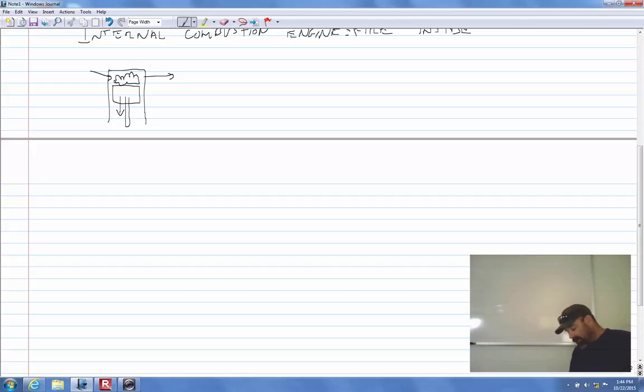And 100 is how high we're going to climb. That's our height, 100 meters. So we do that math, and the energy needed is 981 kilojoules. On flat ground, the energy needed was 450. So literally, it's over double the energy required to climb that hill and maintain that speed.